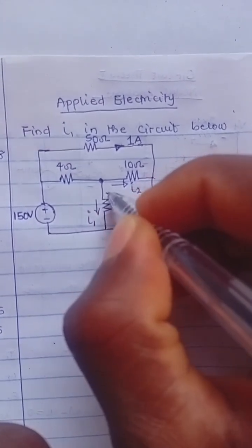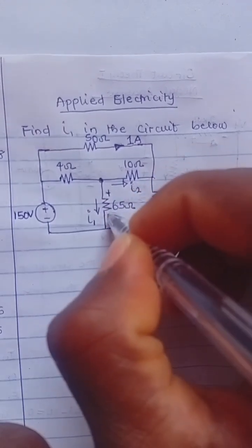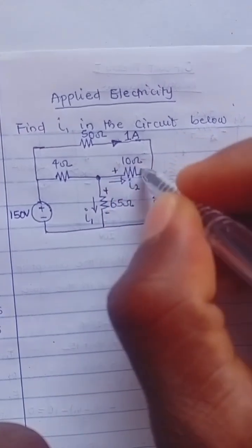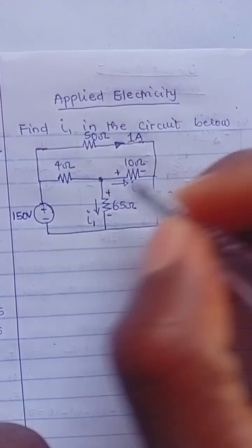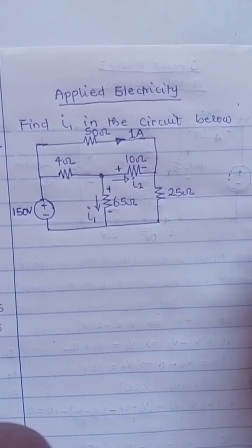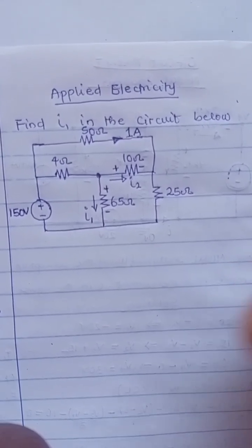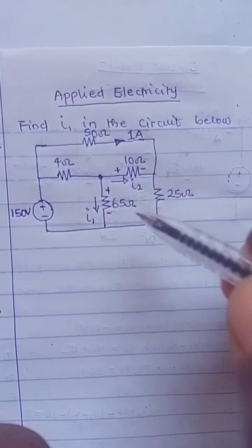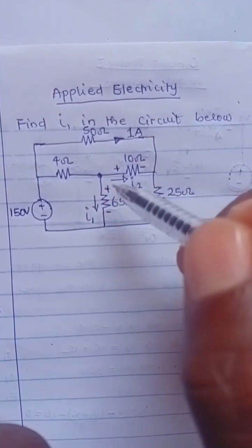So here is going to be positive and here is going to be negative. Similar thing happens here. Current enters at the positive side of the resistor and leaves at the negative side, right? Now these two currents are what I will build the whole circuit currents on. All the currents in the circuit will be expressed in the form of these two currents.